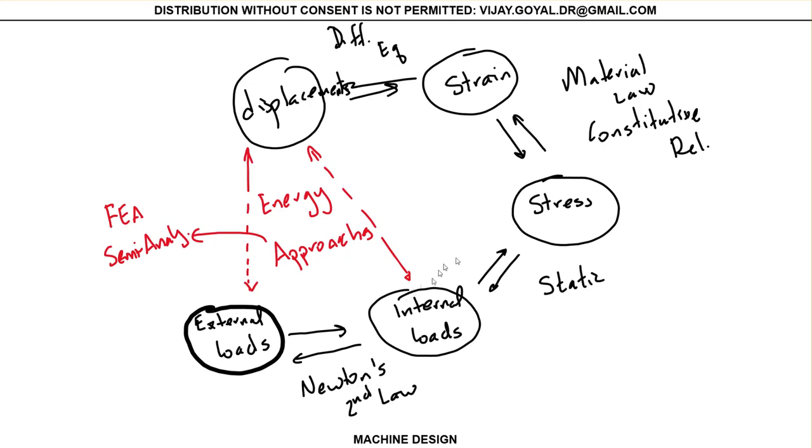So you're going to design something. Typically, when you're designing, you need to know what your stresses are, because we typically use stress-based design. From stresses, we want to see if the structure is safe. Stresses are important because they tell us if a structure will be safe or not. Now, you cannot have stresses if you don't know the internal loads, and you don't know your internal loads if you don't know your external loads.